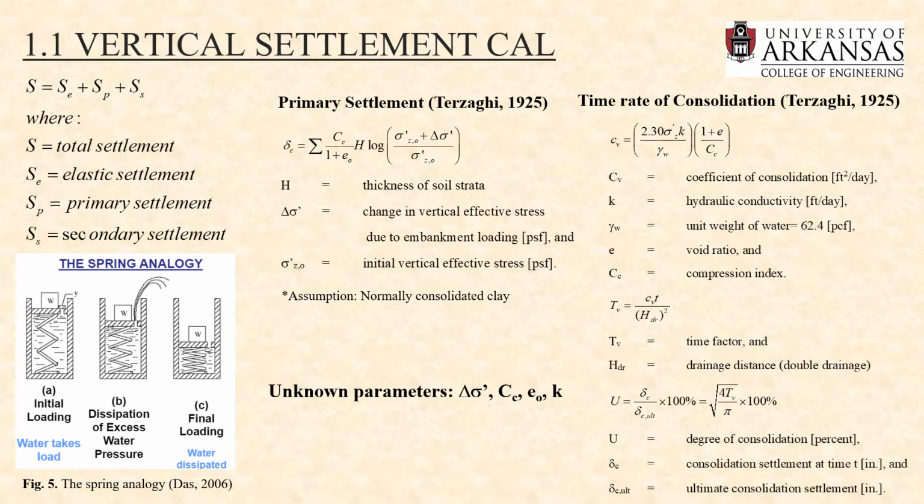for our calculation. The secondary settlement is the settlement caused by the decomposition of the organic clay and the creep effect of the clay layer at the site. Even though the effect of decomposition and creep is really significant for organic clay, I ignored the secondary settlement calculation because our investigating time is only 500 days maximum, while the secondary settlement should be considered for a time span of 5 to 10 years. Therefore, the calculated settlement was based only on the primary consolidation.